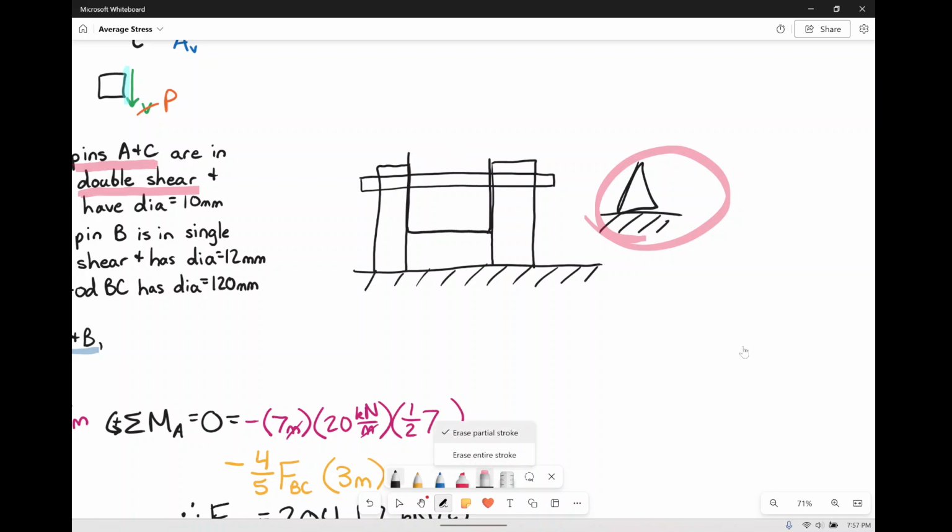Maybe it looks better if it's a bit bigger. So this is our beam, and the rest of all of this stuff here and here, these two blocks and the pin, are actually what that triangle looks like in reality. So this pin's going through the beam, and the beam does get to rotate, right? It's just kind of freely suspended, so it can rotate, but it cannot move in the X nor in the Y directions because that pin's locking it in place.